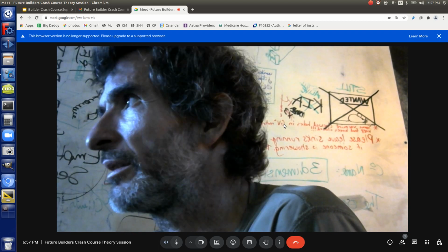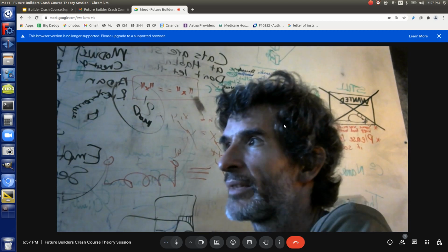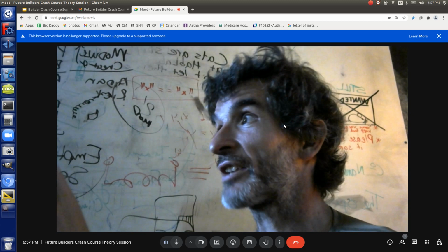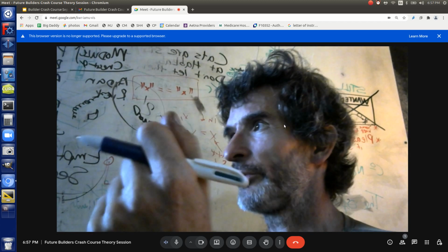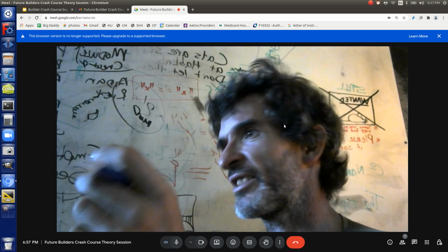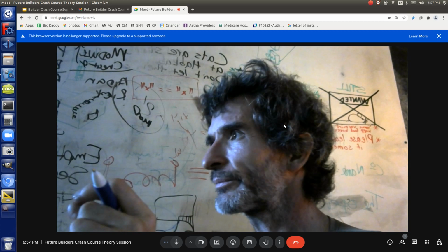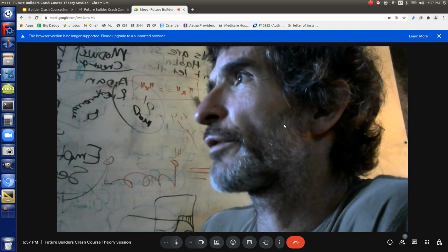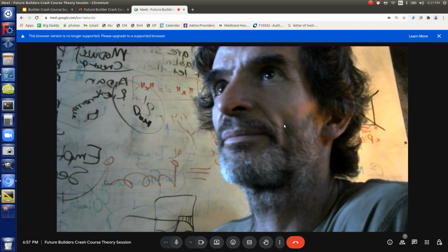After derating we just talked about like 1,000 pounds, right? But they rate nails as about 100 pounds. So now you can start understanding that. You go look at a table and it'll tell you a standard nail, which is maybe 1/8 or something, round thing, is good for holding 100 pounds of shear or pull out. That makes sense. It's a 10x factor.